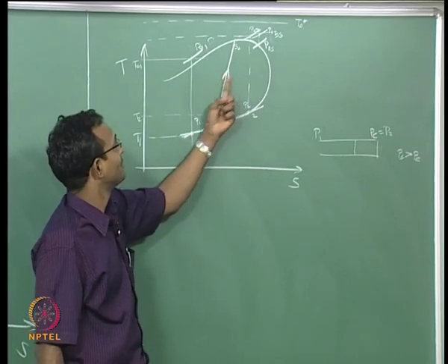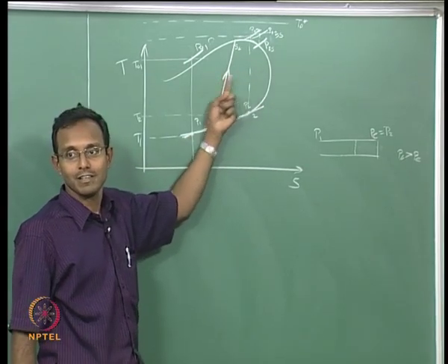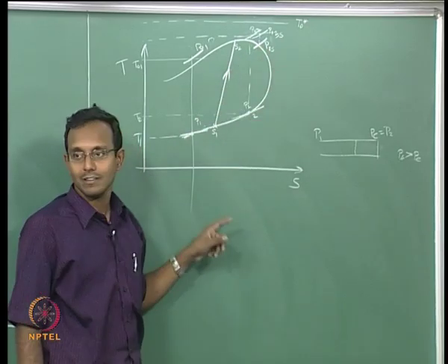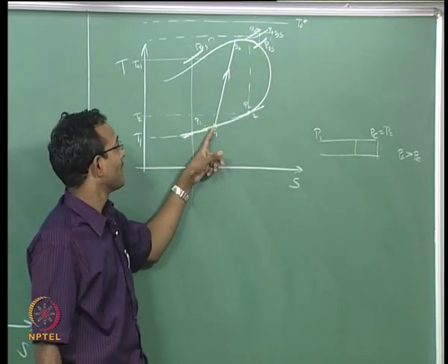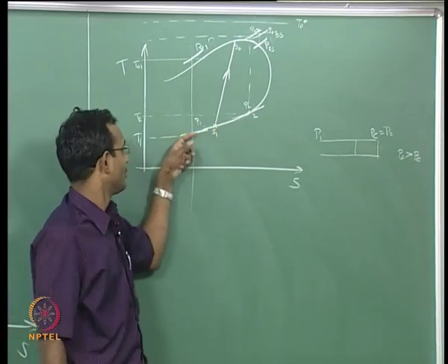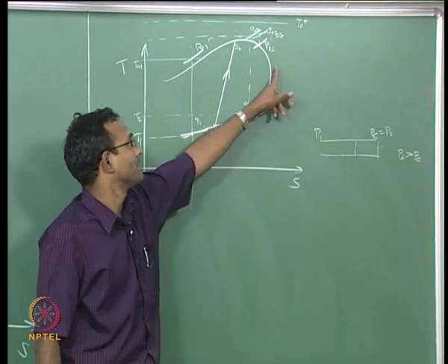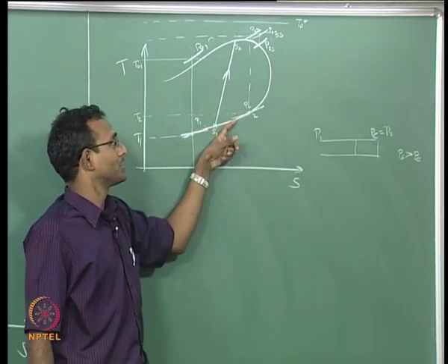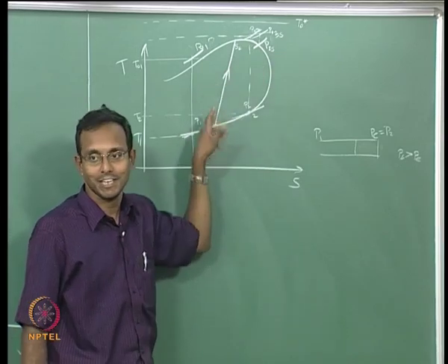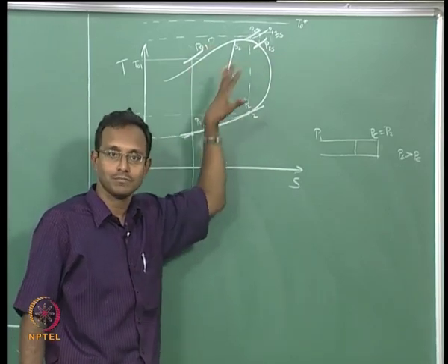So, my shock will shift this way, okay. My shock will shift this way, so that it will go and do that there. That means I am basically saying my Mach number at which the shock happens will now decrease. You remember that here is high Mach number, there it is m equal to 1. My Mach number at which the shock happens decreases. Okay. All this you can just get from just thinking through the curves here.